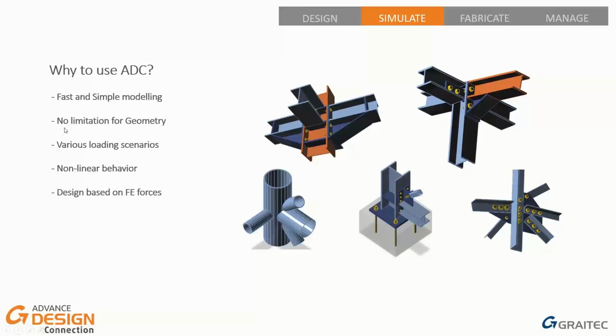Connection. Then there's no limitation for geometry, so you can create any type of geometry very easily, either if it's a complicated or a simple one. You can apply various loading scenarios to your connections in the software. The software is fully nonlinear material-wise, so we can cover the elastic and as well plastic range of your connection. And finally, we also do code check or design based on finite element forces in the software.